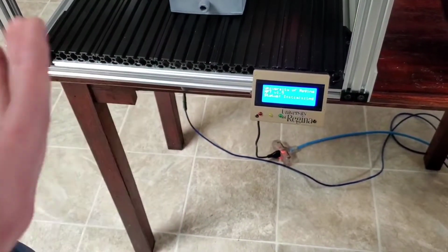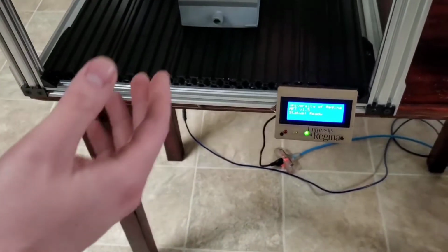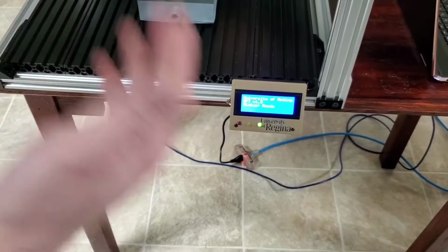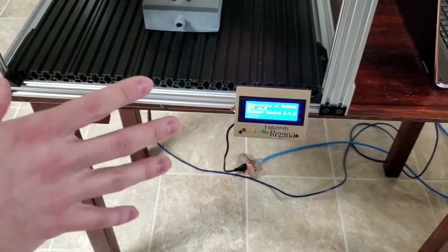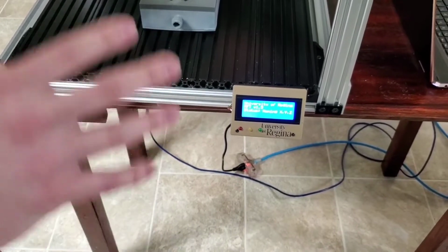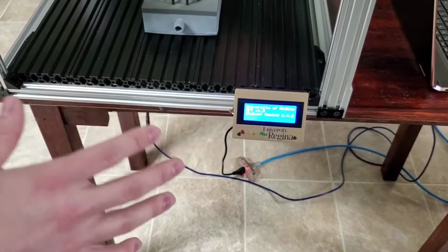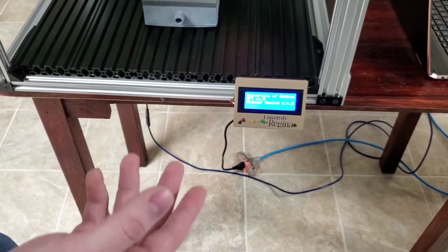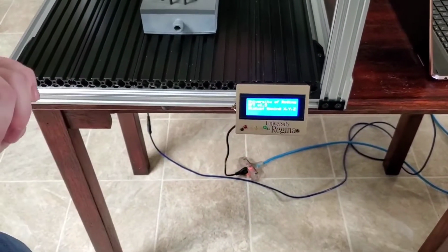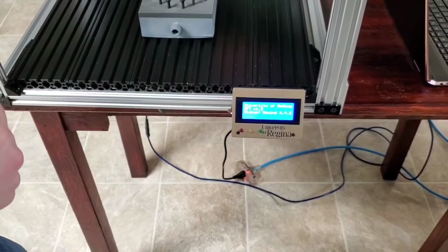Now we're going to kind of show some limit switches. With our limit switches, it's important that our users understand where we were hit and how they can recover from it. So Matt's going to home it real quick here to get us back into speed. Then while moving the X-axis, we're simply going to hit the limit switch preemptively. It's going to think it's hit a limit switch. It's going to enter a fatal error, and then we'll obviously require a reset.